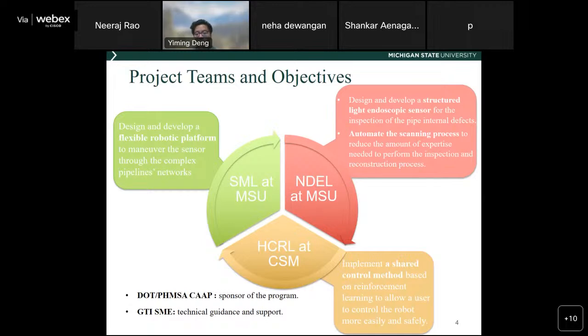It will give you surface features in a plastic pipe that is featureless most of the time. We call it featureless because the surface of a plastic pipe is very smooth, so it's very difficult to do a data reconstruction while handling the correspondence issue, that is, knowing where your sensor is when you are taking the data.